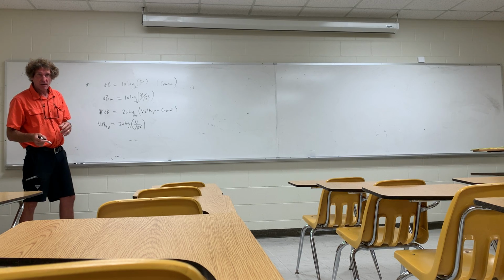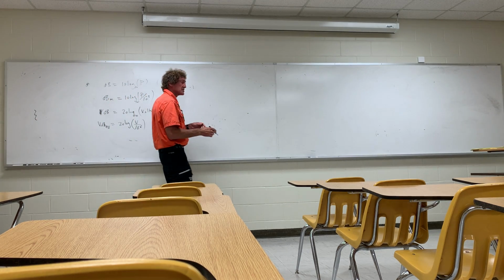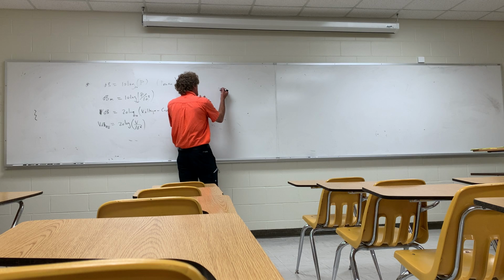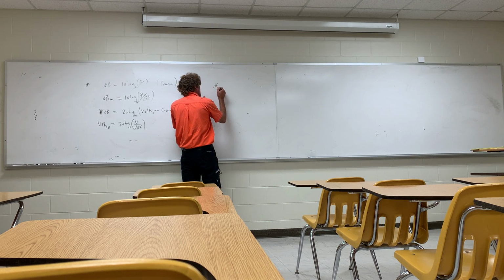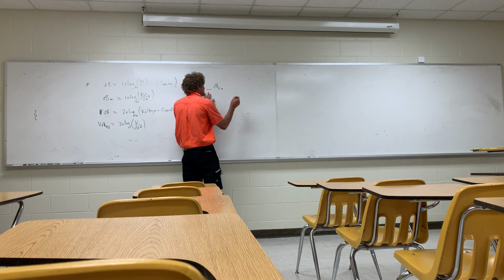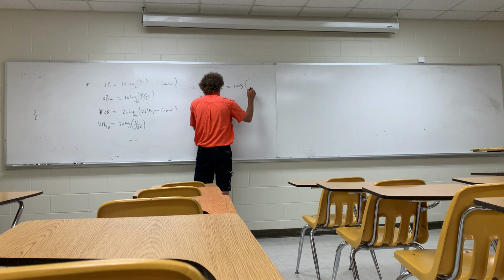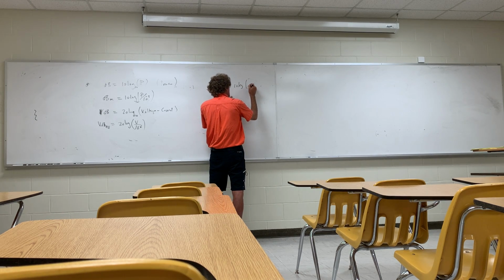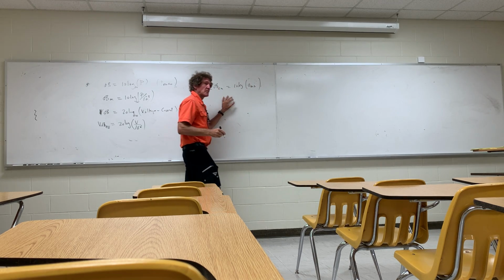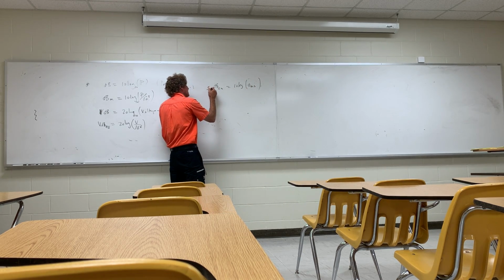Just remember that. Now, when you talk about radar cross-section, because it's related to power, dB, and it would be square meters usually, where the quantity here will be dB square meters. That's 10 times the log of the quantity. In this case, it's cross-sectional area, right? It's sigma RCS. Y'all follow me? This would be sigma dBm.